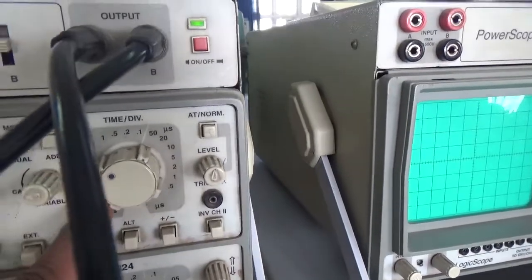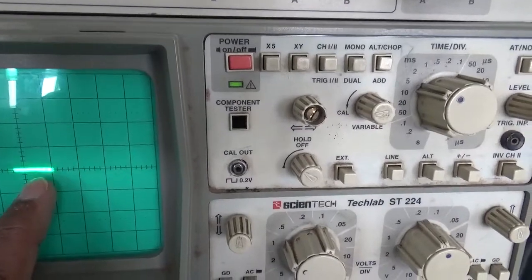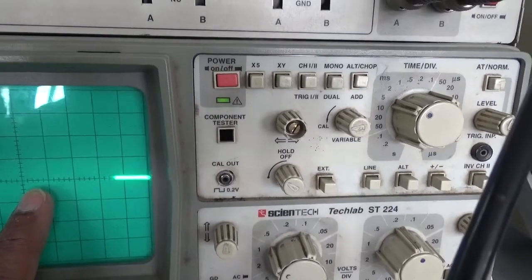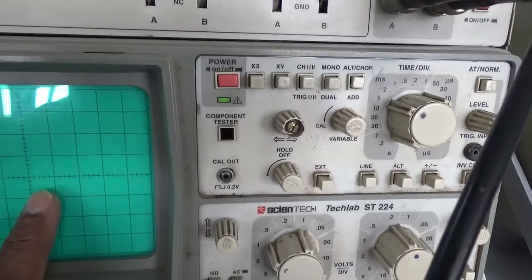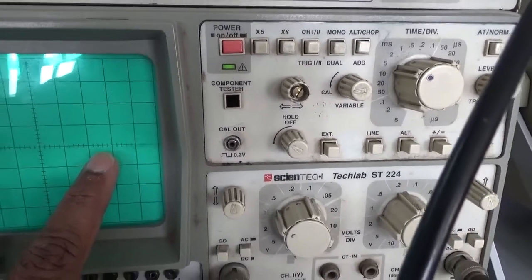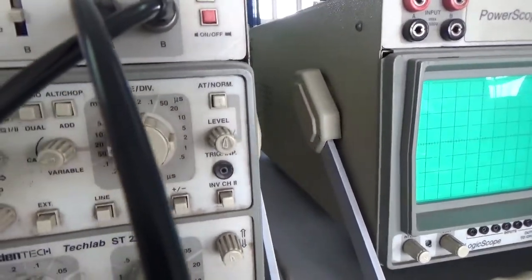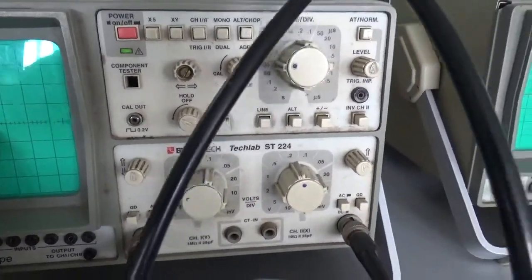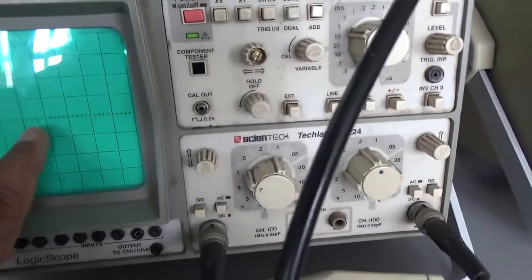Whenever you put it at 5 millisecond, it means that every time division is 90 degrees. This is 90 degrees. So 5 millisecond means 90 degrees, 20 millisecond means 360 degrees, because supply frequency is 50 hertz, inversion of that is 20 milliseconds. So 20 milli corresponds to 360 degrees. So we have put the time division to 5 milli. 5 milli means every unit is precisely 90 degrees. If at all you put it at 20 millisecond on the knob, then every unit corresponds to 360 degrees. So let us keep it at 5 millisecond, and we can see the firing angle properly.